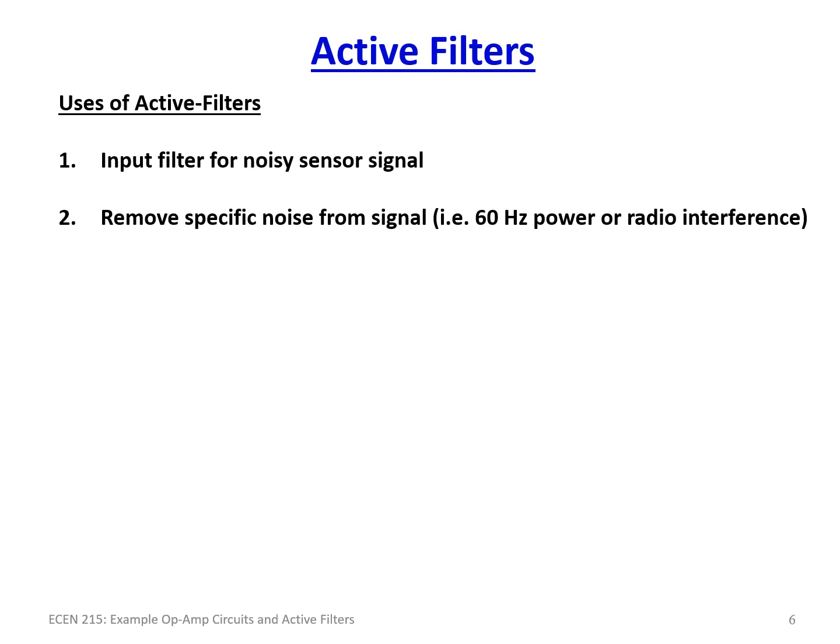You can also have the need to do, say, a band reject filter and specifically get rid of certain very specific signals. For instance, it's really common to use a 60 hertz band reject filter if there's a lot of power line noise coming into a signal, to reject the power line frequency.